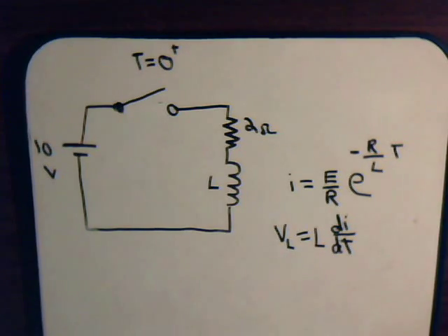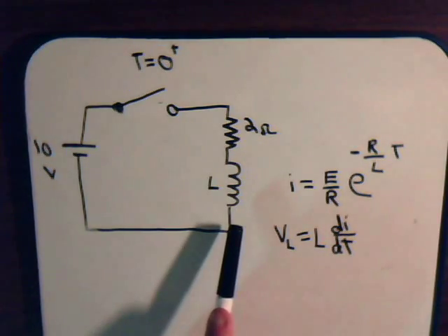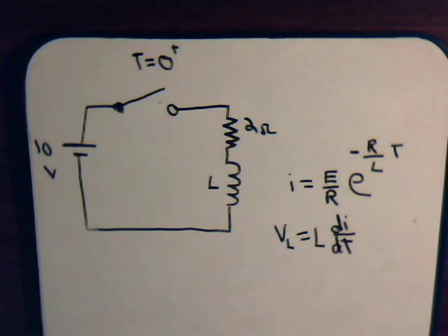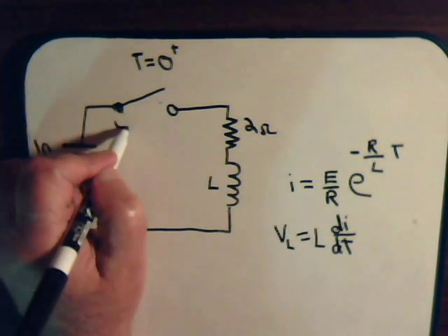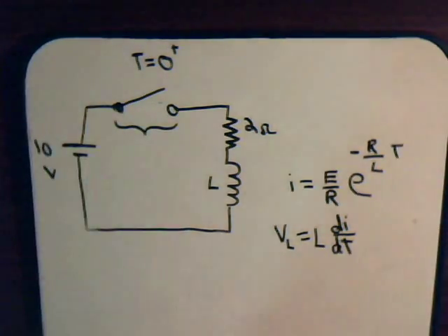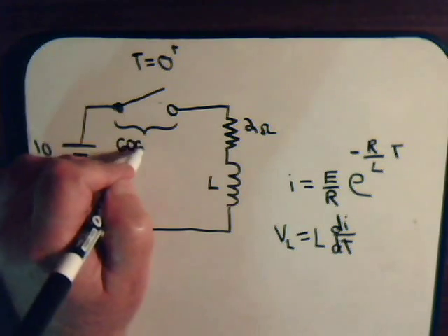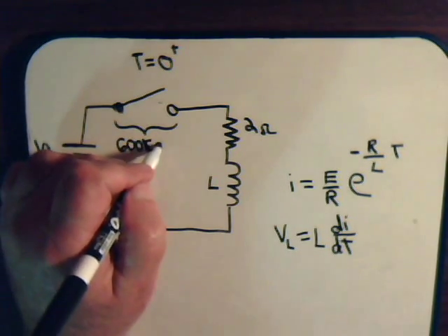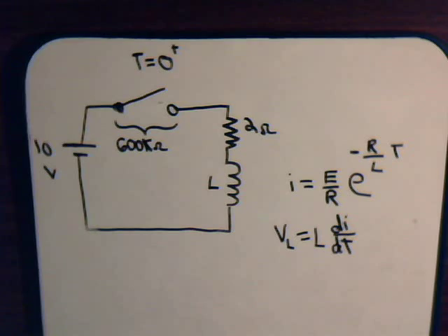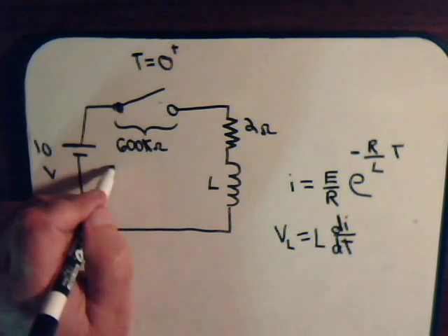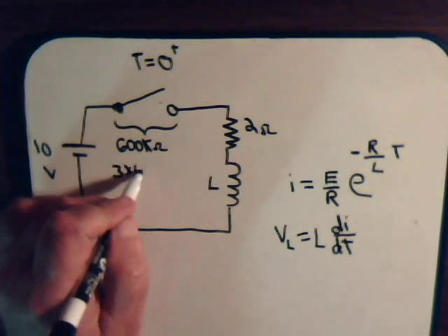If there's 5 amps of current here, it's going to try to push that 5 amps through the entire circuit, so it has to go across this gap. Obviously this air gap is going to have a lot of resistance, say maybe 600,000 ohms. So if there's going to be 5 amps of current going across that gap, that would mean a voltage drop of 3 million volts.